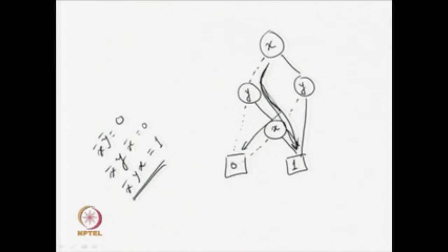So, though our basic definition of BDD is not restricting the occurrence of variables any number of times in any places, we may face problems. So, in that particular case, what happens? We have to come up with the notion of consistent paths, and when we look for the evaluation of this particular Boolean function, it should be evaluated through the consistent path only. We should not evaluate it through an inconsistent path. So, that is why this is one inconsistent path, because here x equal to 0 and x equal to 1, which is inconsistent.